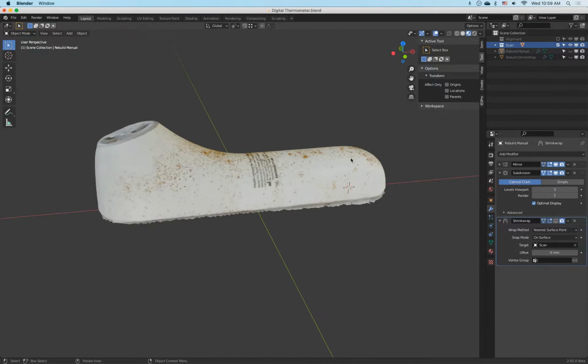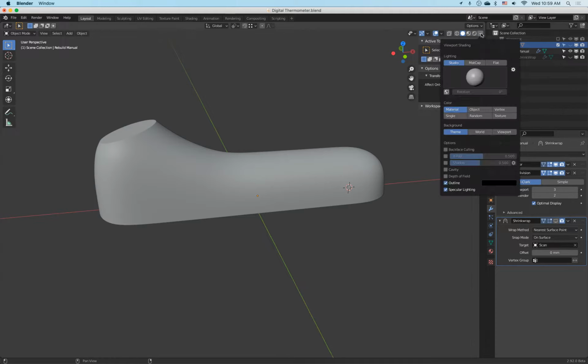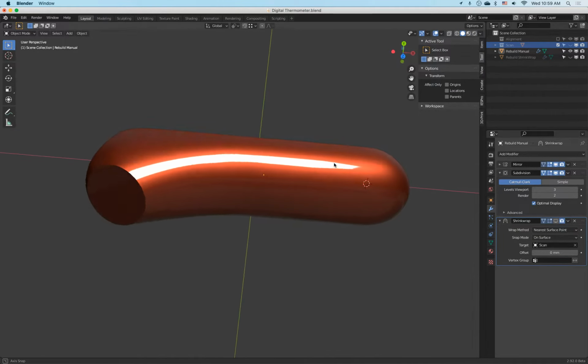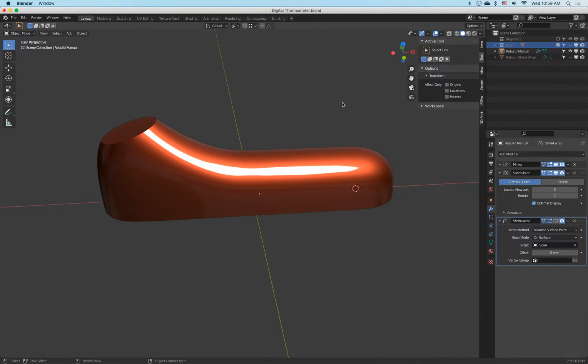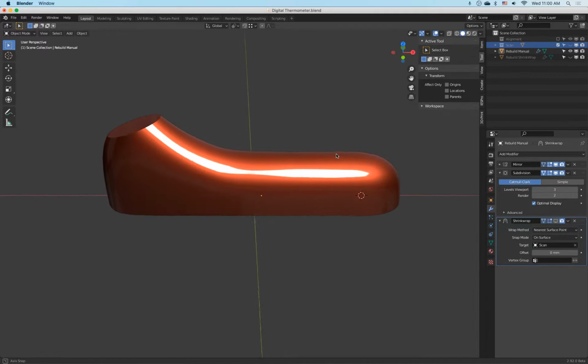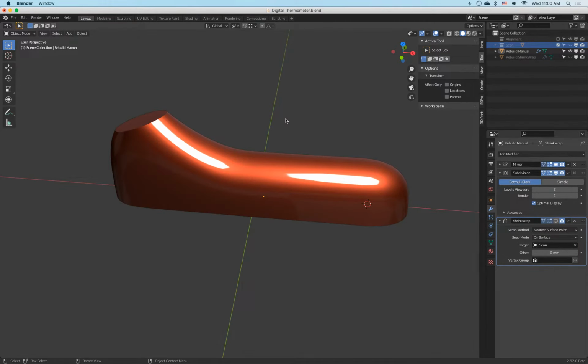And then that mesh can be placed into any program. Here, the thermometer is inside Blender, can be loaded into Fusion, anywhere that can load the mesh. And then we can use this as a three-dimensional blueprint to, for example, create a nice and clean version of it. This is also an amazing tool when you have a form model you would like to prototype or an existing object you would like to digitize. It beats hand measurement and then trying to transfer that into a 3D program, which is labor intensive and prone for errors. And via the photogrammetry process, it's literally a matter of maybe 10-15 minutes and you're done.